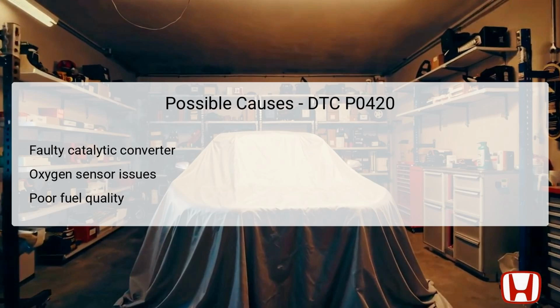Additionally, poor quality fuel can contribute to the buildup of deposits in the catalytic converter, which hinders its performance. It's important to address these upstream issues before replacing the converter itself, as doing so may lead to further complications. Diagnosing the correct issue can save time and resources in repairing the vehicle.